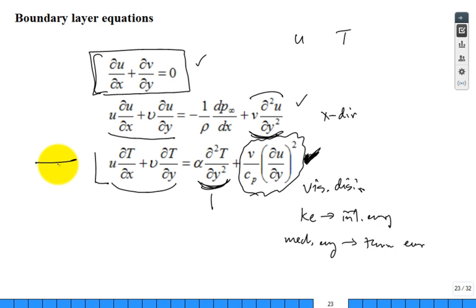Because this energy equation is not the complete energy equation in the sense that you're not tracking the changes in kinetic and potential energy. You're just changing the enthalpy or the internal energy, so this shows up as a source term in our energy equation. Why? Friction, and the mechanical energy is being dissipated through friction.